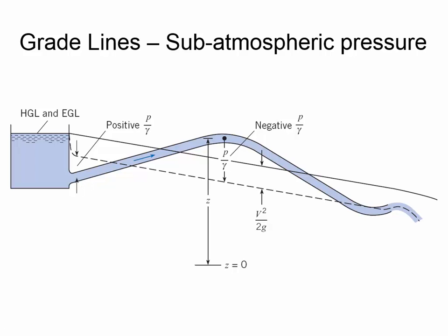That is, the EGL and the HGL are not affected by where the pipe is. The only thing that affects the slope of this line is the rate that energy is being lost. But think about where the energy is. There's three places. I've told you before that the energy can exist as pressure, elevation, and velocity. So when water inside of a pipe is going uphill, this is a pressurized pipe, and so the water is flowing uphill because the pipe itself is increasing in elevation. You're gaining Z, but you're losing pressure when the pipe gets higher. But the EGL and the HGL, it doesn't matter because both elevation and pressure are in the HGL. So although the physical elevation of the water is increasing and you're gaining Z, you're losing pressure head at the same rate. And so here you can see that the HGL is steady.